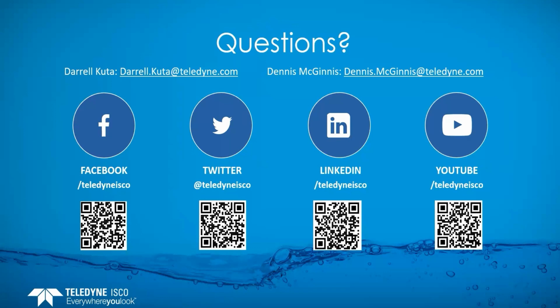Yes. The modems in the meters, as long as you've got your meters set up with their texting ability, technically we can set up the modems in the meters to actually send the alarm directly from the meter to the end user. So that isn't using Cipher at all. That's really the meter just monitoring itself, looking for that programmed alarm you have in it, and then upon that alarm it'll wake up and shoot out a text message for your alarm. So yes, you can receive alarms without Cipher. You can do it just from the modems in the meter, but you will need modems and texting subscription or texting ability in those accounts.